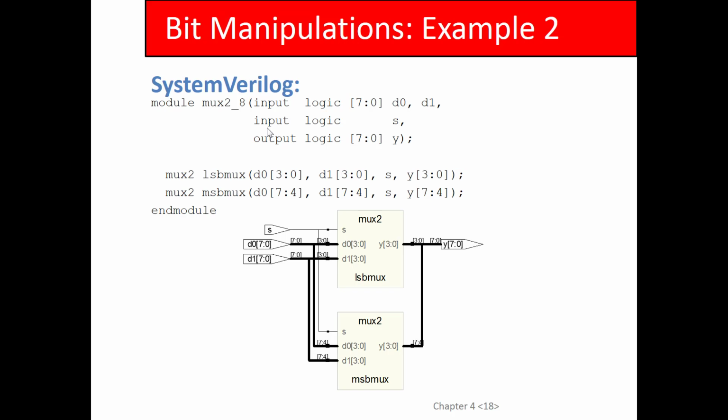Now you have to be careful when you do this, though, because I think I mentioned last lecture that each of the bits of Y can only be set by one module, right? So normally, if you had Y connected to both of these, you would be double driving it.